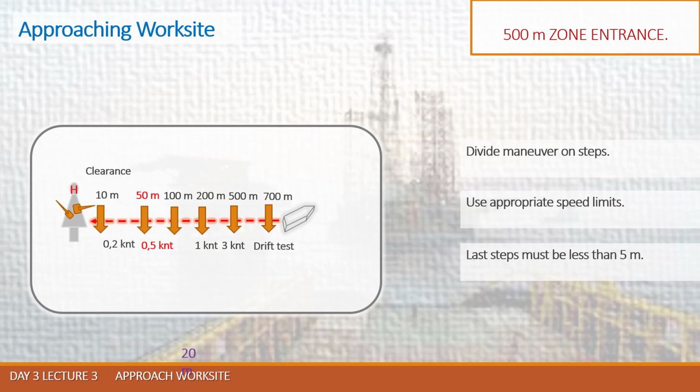All of that time, while we are on maneuver, we proceed adding each waypoint or set point in advance without stopping the vessel. But from 50 meters, we proceed with a speed of less than half a knot, better 0.2, 0.3 knot, and we proceed with a maximum set point of 5 meters per one set, expecting performance per each set point.